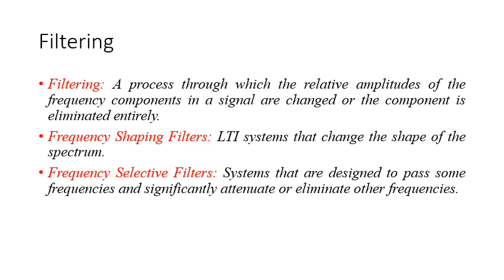In the case of frequency shaping filters, the LTI systems change the shape of the spectrum. For example, in an audio system, the LTI filters can modify the relative amounts of the low frequency energy, or they can modify the high frequency energy.